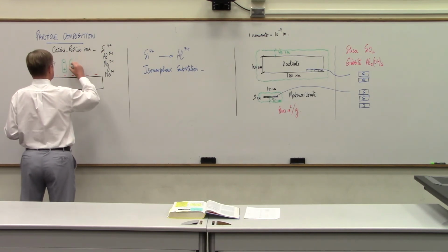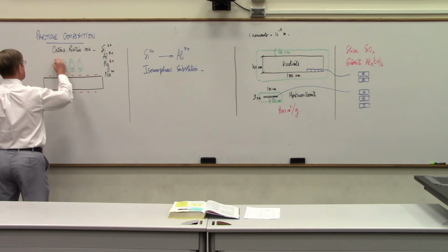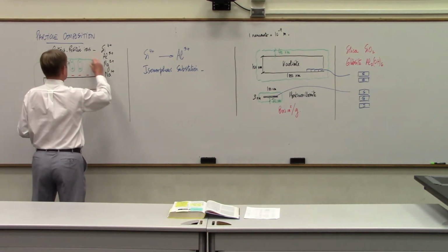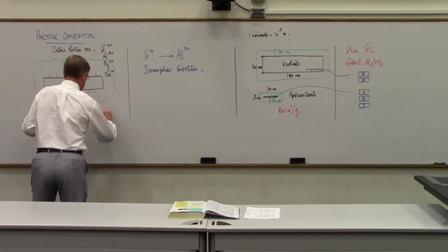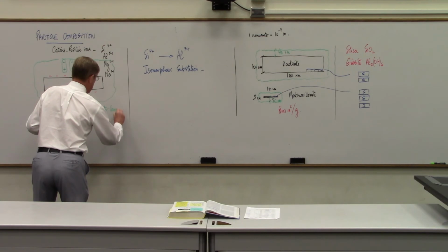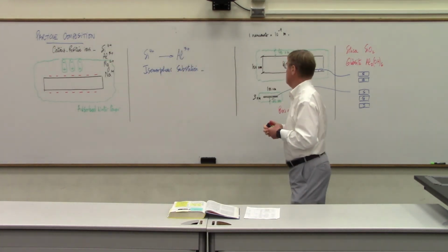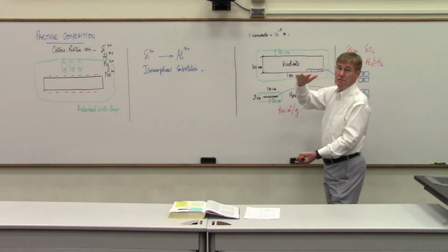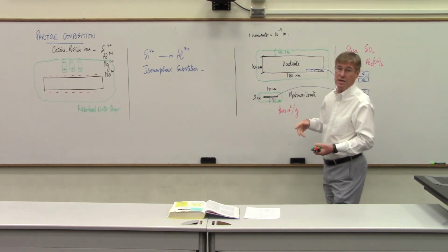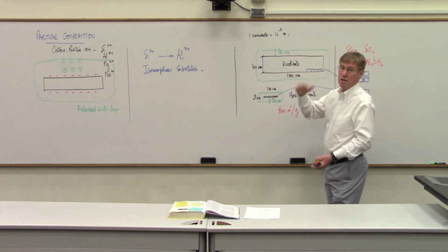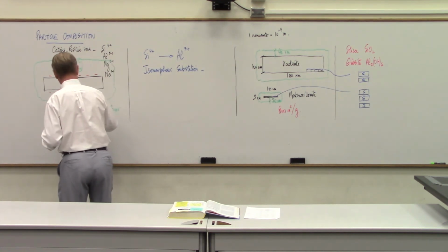So then these water dipoles will start coating the particle, and in doing so, they form what is called the adsorbed water layer. So again, question, what is the adsorbed water layer? And you can imagine that the adsorbed water layer on the montmorillonite is going to be very large compared to the thickness of the particle, compared to what would happen to the kaolinite. So kaolinite can swell, but not much. Montmorillonite can swell a lot because of this huge area that's available. So this is the adsorbed water layer.